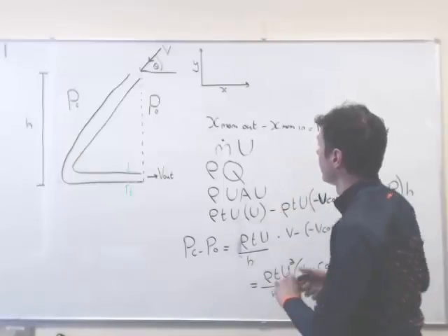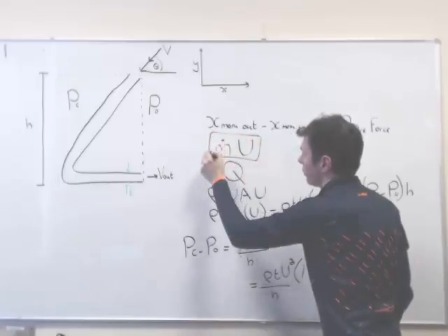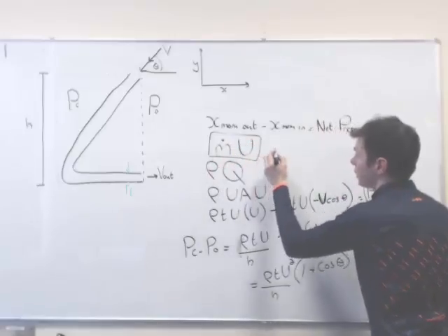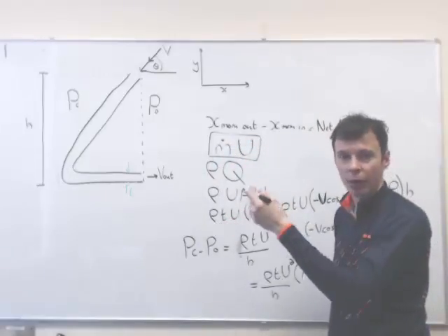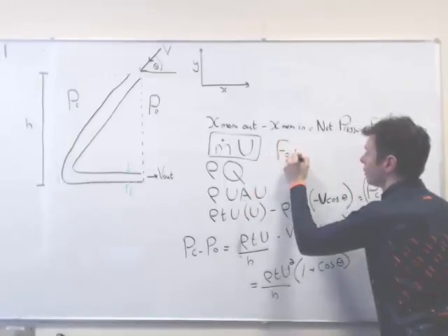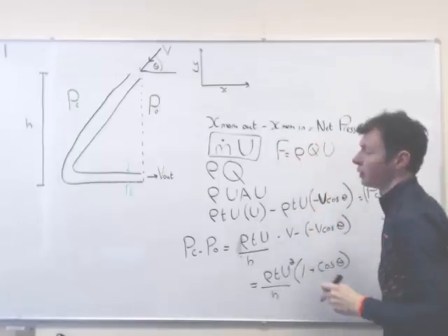Again, this is the general form in terms of force that we'd use. So the mass flow rate, kilograms per second, times the velocity. Often, if we're working out force in, say, a pipe bend, something like that, you generally write force equals rho Q times velocity.